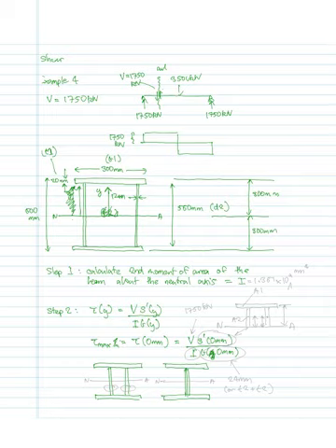So b, in this case, because we're talking about a stress, must be equal to 24 millimeters, or T2 plus T2, because we're calculating a stress, so we do need to take into account both webs in an additive manner. And then the S dash y, that's going to be about the neutral axis again.